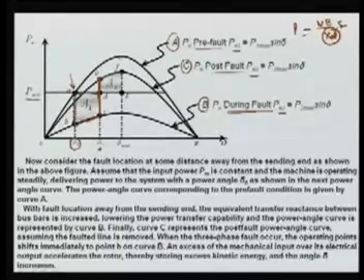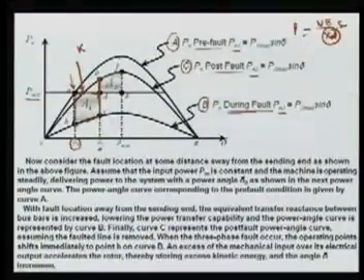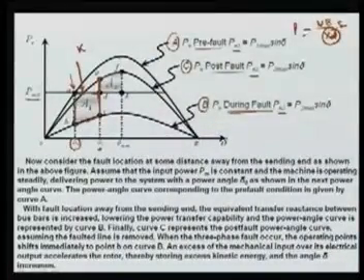equal to A2, and then again it will go back and then it will be again oscillating, and your final point of operation will be now here, it is your K point will be the final point because it will be oscillating around this point and your system will be stable if your damping is there and the system will subside. So this is the condition when it is the fault, means this is during fault, this is a post fault, this is a pre-fault.